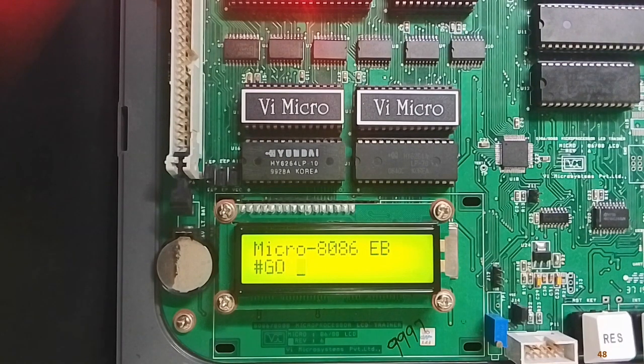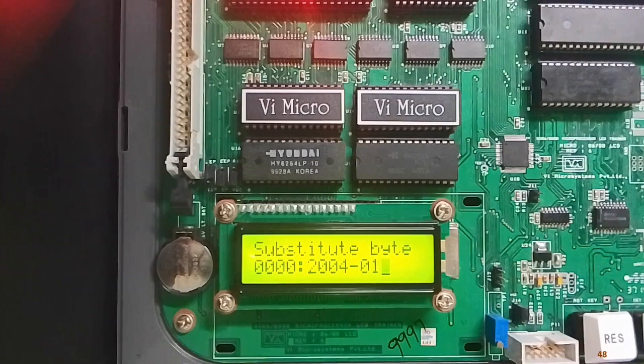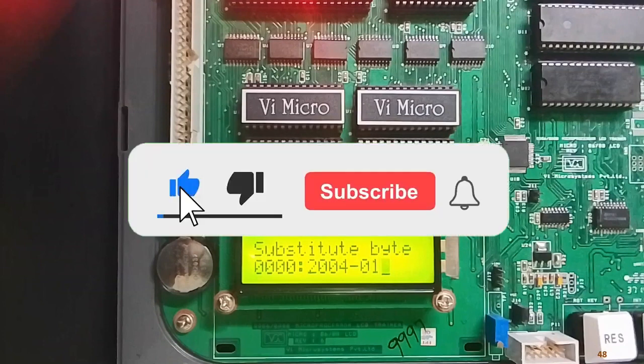So I have to give the go command and after that the starting address of the program, executing, reset, and SB, the memory location of the data which is getting saved. After that, it is going to be 05, 04, 03, 02, 01. So it is in running order. I can see all those things one by one. This is how I can use the same values, same location, and sort the array in descending order. The only change you are going to make here is jump carry and jump no carry, for ascending and descending. Thank you for your patient listening.